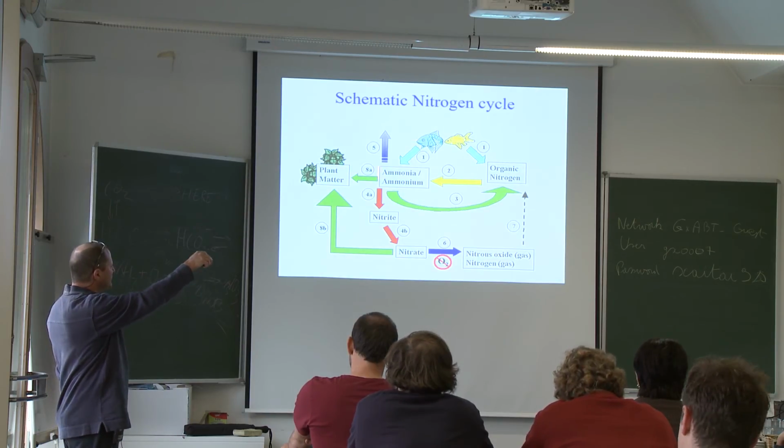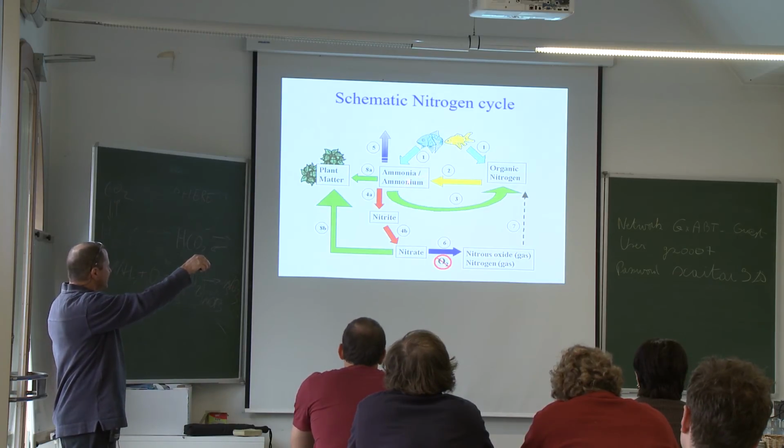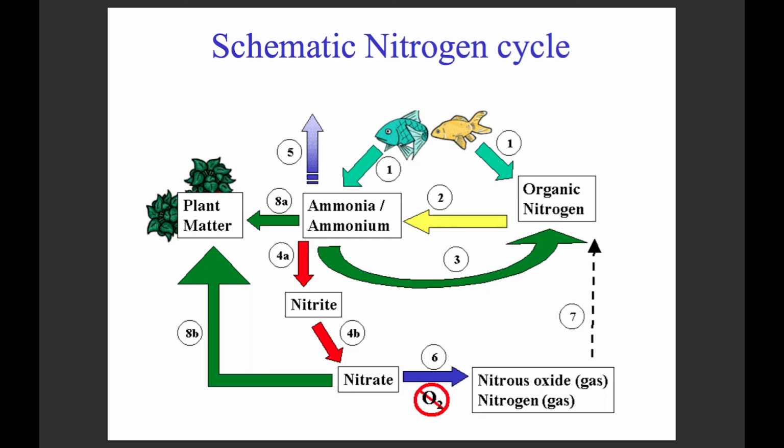So in this case, we have fish, as we said, where they excrete ammonia. This is our source. Mostly, as we said, nitrification to nitrate, and on the way, if we want to remove nitrogen, we mostly denitrify it, to nitrogen gas, by either denitrification or anammox or different processes.